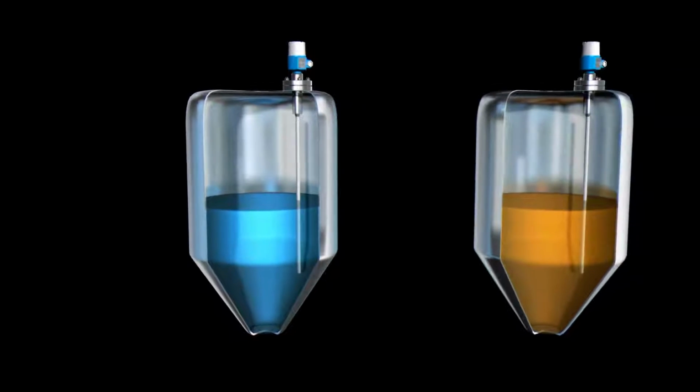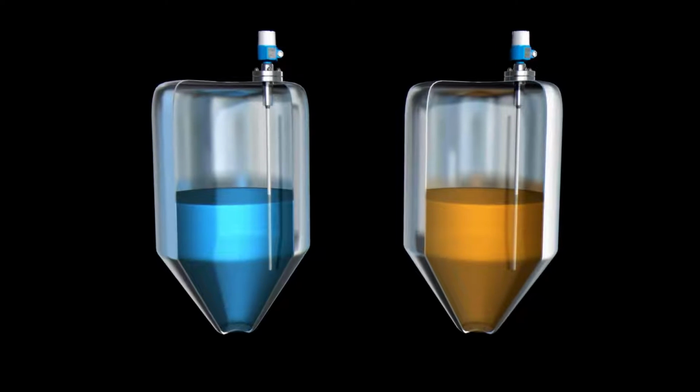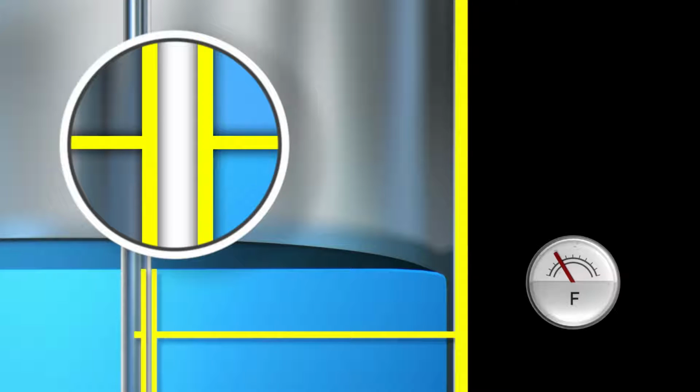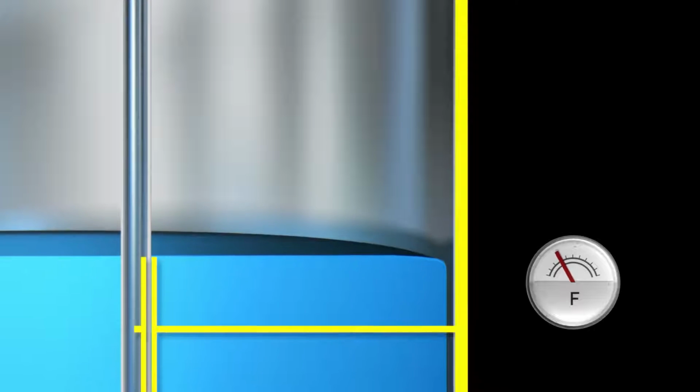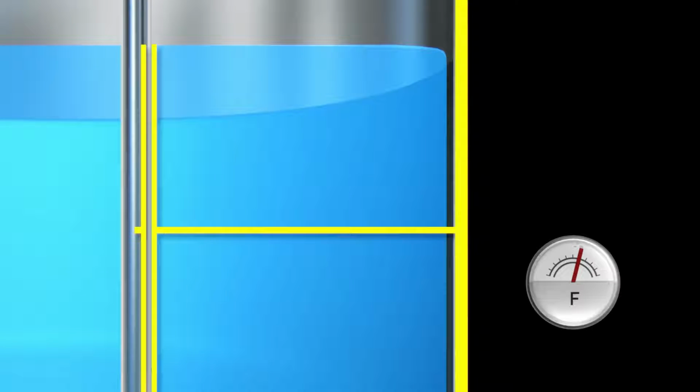In capacitance measurement, electrically conductive liquids and non-conductive liquids are differentiated. Measurements in conductive liquids, which are normally water-based liquids, are carried out as follows. The medium forms an electric short circuit from the tank wall to the probe insulation. Therefore, the measurement effect is only formed by the probe insulation capacitance gained from the media. This provides stable measurement which is independent of the tank geometry and the dielectric constant of the medium. If the level rises in the tank, the area of the capacitor increases proportionally. The measured capacitance change is used to determine the level.